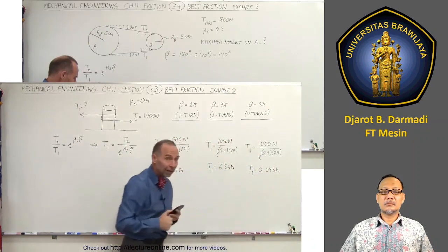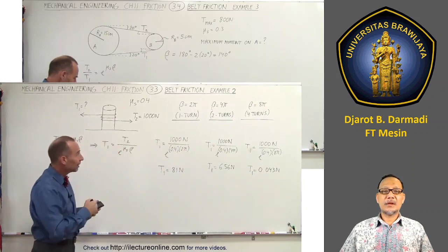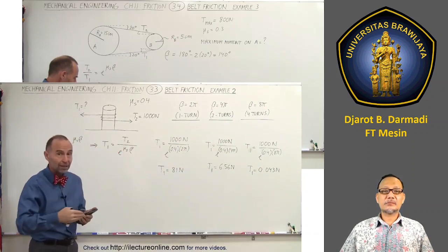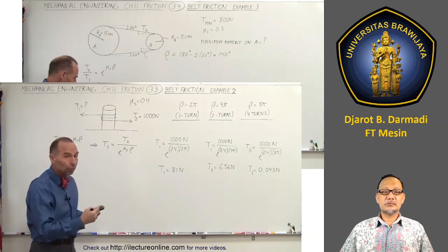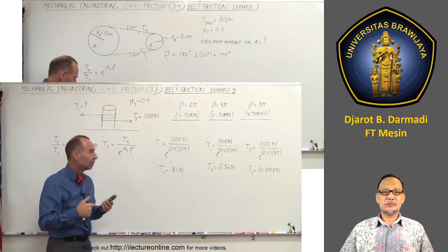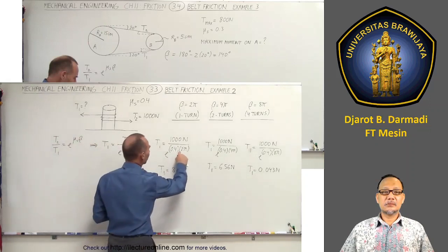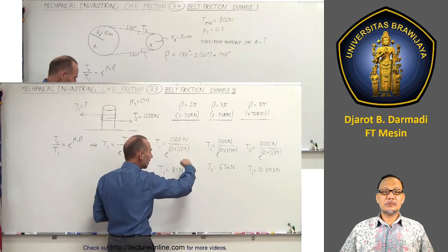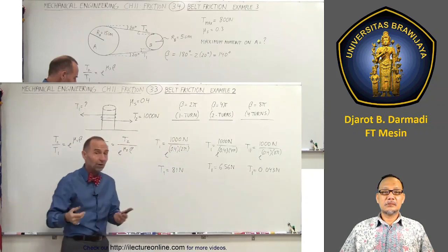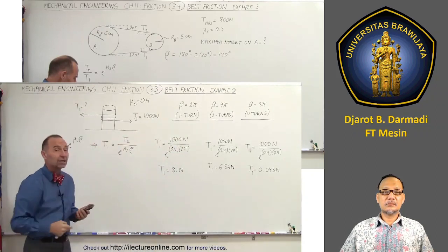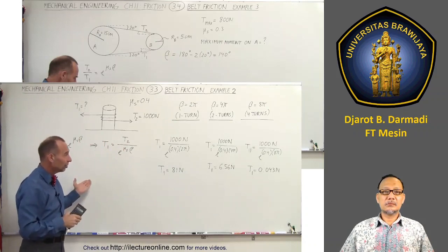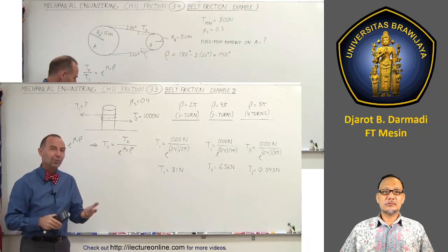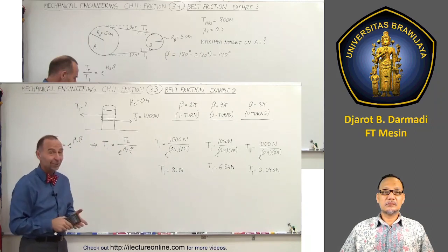Notice that if you compare this to the previous example, doubling and quadrupling the coefficient of static friction had the same effect as doubling and quadrupling the number of turns around the post, because both of them are part of the exponent of the number e, and because of that, the tension required to keep the rope from slipping dramatically decreases. And that's how you can see the relationship between the tension, the coefficient of friction, and the number of turns in the rope. And that's how it's done.